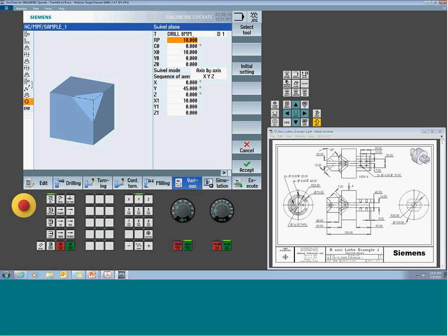I can leave that in, that's fine. I retract. Now I'm not bringing my X up 10, this corner. I'm bringing it all the way up to the surface, which is 25 mil out, right? Give it a positive 25. Shift back is going back to this corner, so I'm sliding my zero back. Zero pointed straight out from the surface, 40 mil, that's a negative 40 mil in Z.